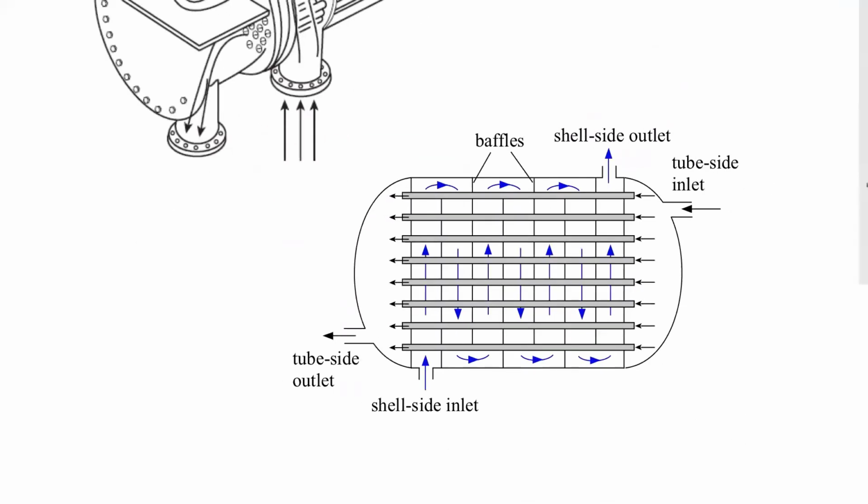You might go in there and put in, okay, I have a shell and tube. My shell has 1, 2, 3, 4, 5, 6, 7 passes. So you'd specify the number of passes that it has, or sometimes it would be like 1, 2, 1, 2, and 3 passes. You have to look at the correlation itself. But this will give you some empirically derived correlation that you can use to predict heat transfer in this particular geometry.